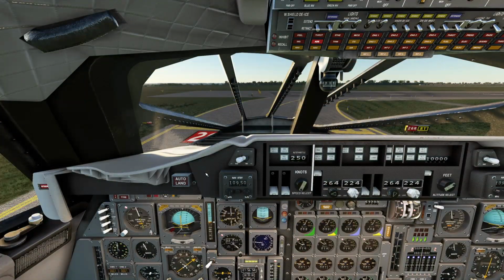We're at the holding position of runway 26 right. We have to do a few checks and turn on lights, and then we're gonna put the visor and the nose down once we're on the runway. We should have done that for taxi, but it might get an annoying alarm if you have your engines on standby or on idle. So we're gonna do that on the runway.